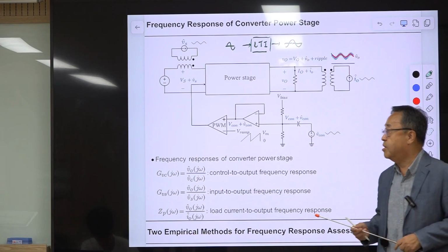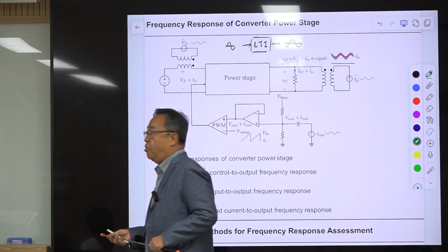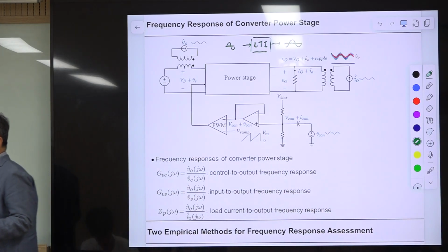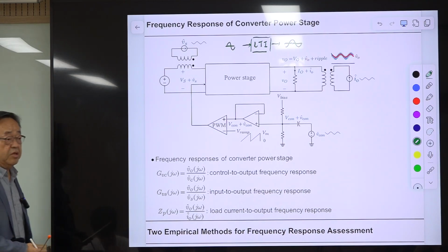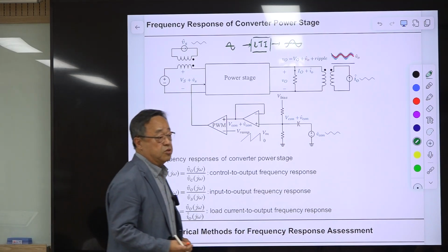That is defined as the frequency response of a linear time invariant system. And the frequency response contains all the information, static or dynamic, about the system, and one particular most important outcome is the transfer function of input to output variable, which can be used to evaluate the stability and the dynamic performance of the system.